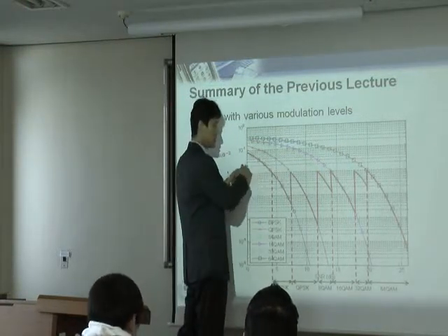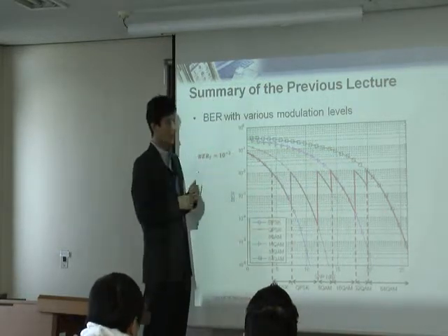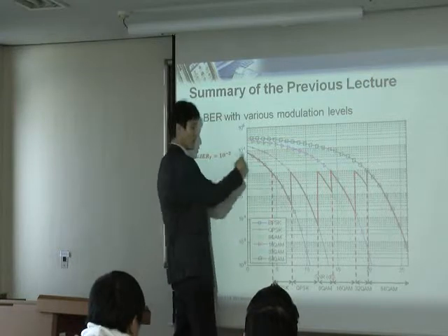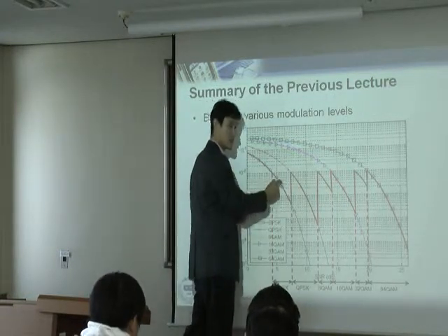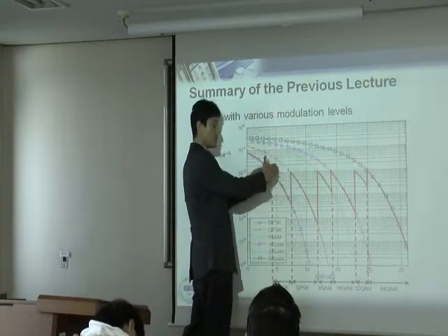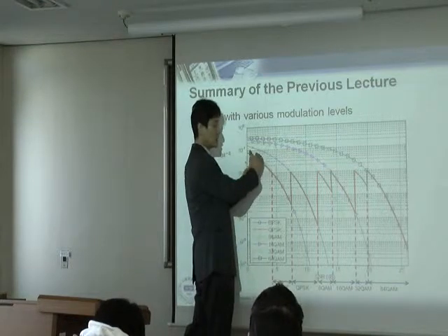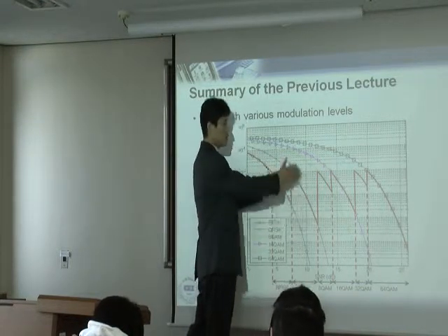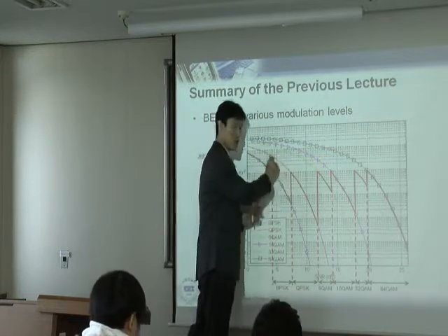So putting those things in simulation, you have 15 different curves. Once you do that, what you can notice is that all the 15 simulation curves are not equally distanced. Some of the combinations, for example BPSK with some coding rate and QPSK with a lower code rate, maybe almost overlap.